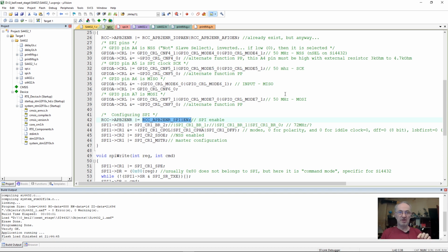For this reason, unlike I2C, where the line is high by definition, or by a resistor, or by a device you power, this time we should implement a resistor to pull the line up. So for example, in this specific case, 2 masters each communicating with this device, arbitration decides: whoever first pulls this wire has the right to communicate.